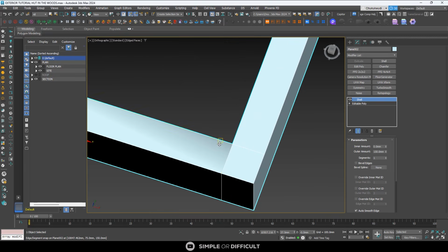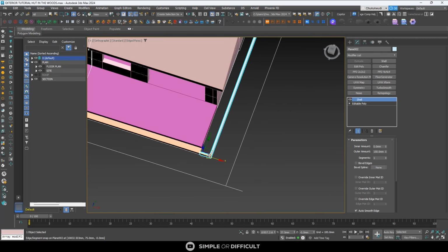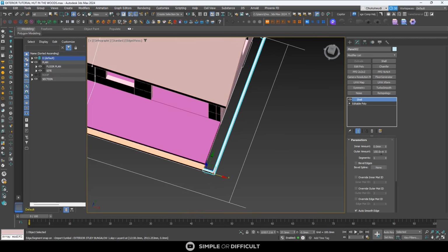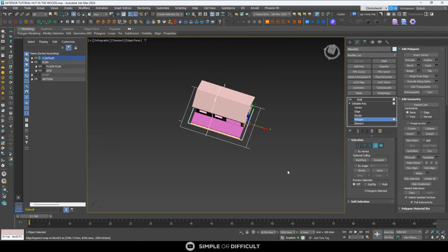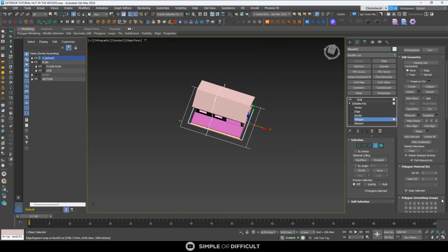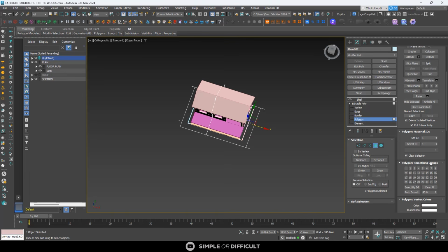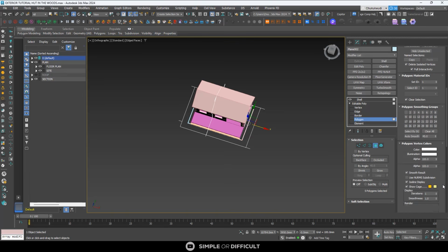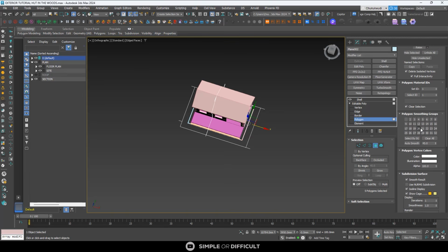When you look here, you're going to see there's this funny color, like a shadow that you're having here. This is exactly what I was trying to explain when we modeled the wall. I told you that if you do not come over here, use polygon smoothing groups and all that, and adjust this to clear all, you will have something like that.